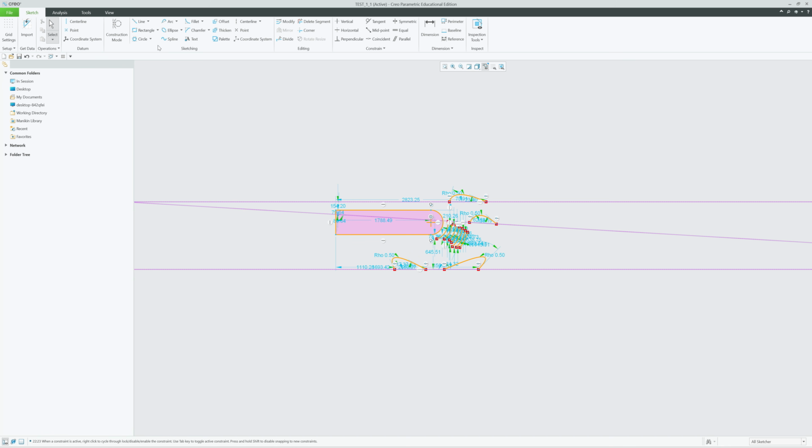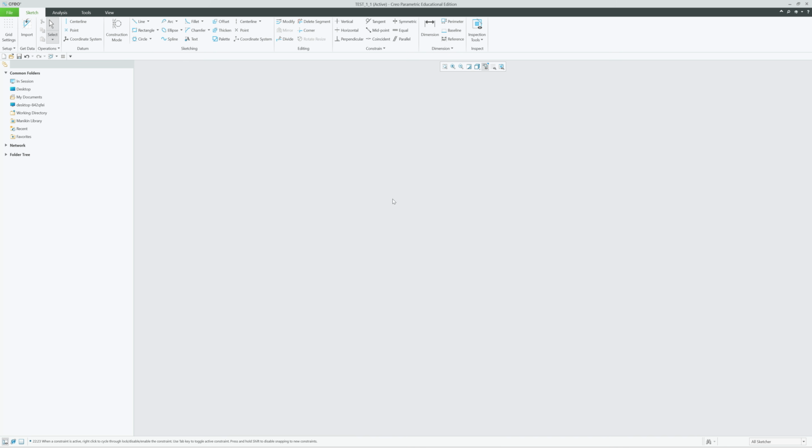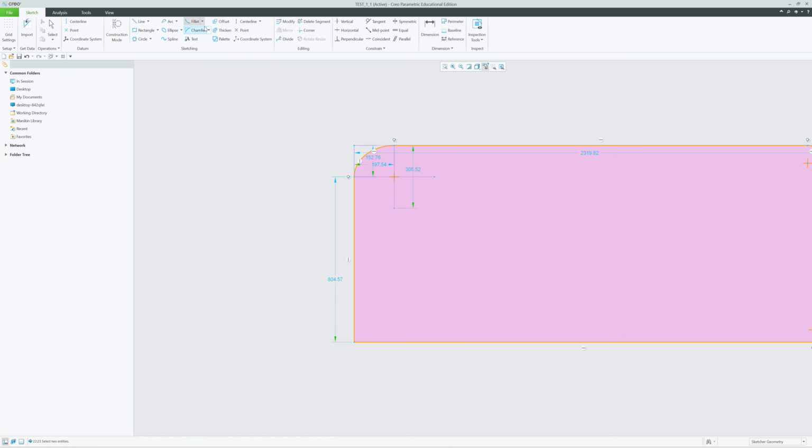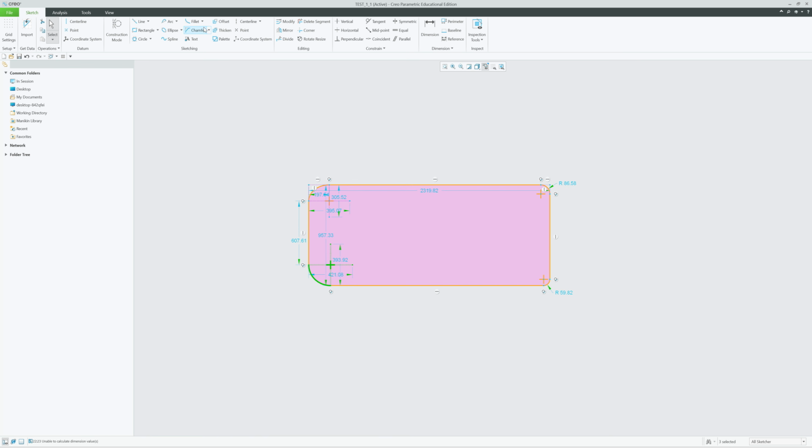So these are all the construction options. I'll show you another 2. Those 2 also are construction options. And then we go for the modification. In the fillet we have circular fillet. We just select 2, and it will become circular. And then circular trim, and then elliptical trim. So these are all the different things you can try on the fillets.